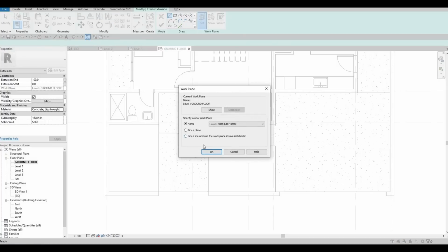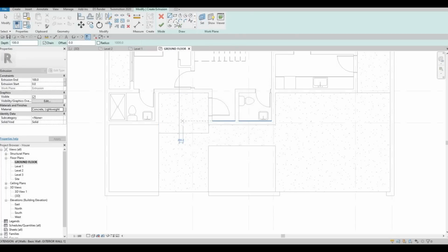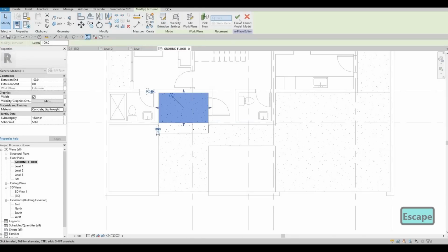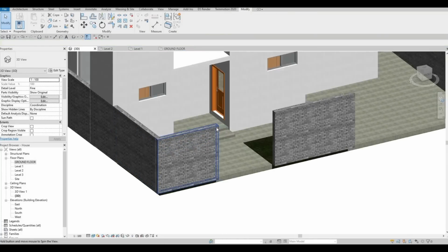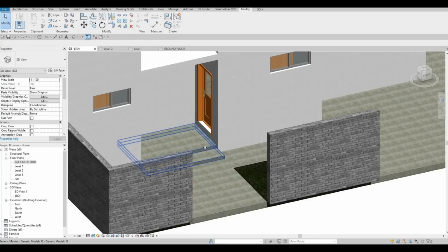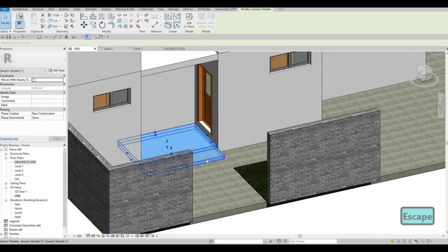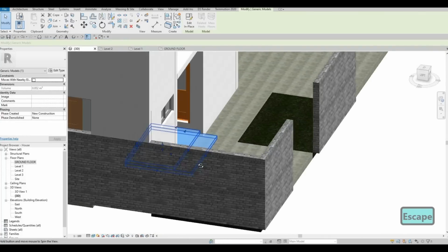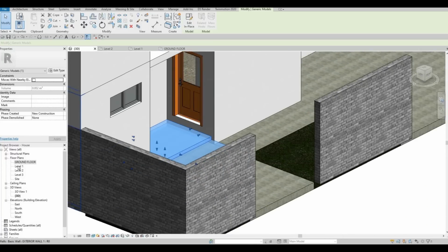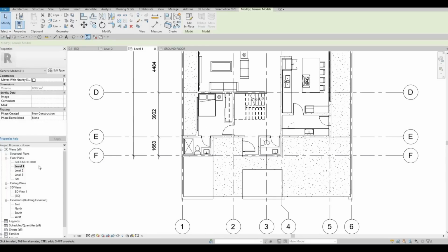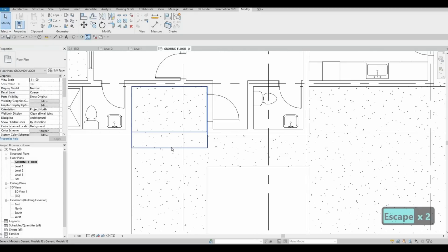Let's set the plane. We're gonna pick the plane on top of this, and then we're going to add another one. So now we have our stairs, and it will be another 100, and now we could click on finish, and here you go. We could basically add an extrusion of 150 or 200 each, so that we could come up to the level there.